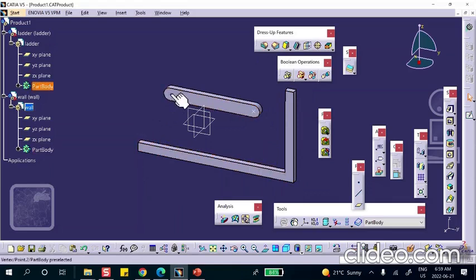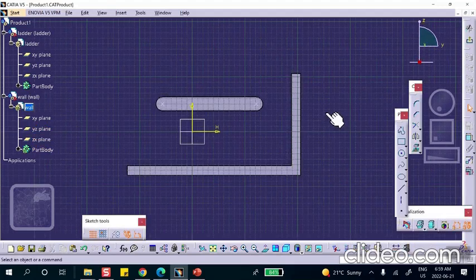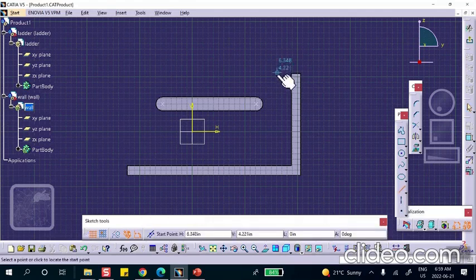Now, I'm not going to worry about that because I will do slide curve joint, which is that curve at the end slides along that line. But for this point, I'm going to do a point curve joint. So I'm going to draw a line, straight line here, which is half an inch from the wall. And eventually I make that point to always slide, not slide, but move along that line. So here's the reason that I'm going to make this line for you. I just explained it. So on that plane, on that vertical plane, I will sketch a line like that. Okay, something like this.